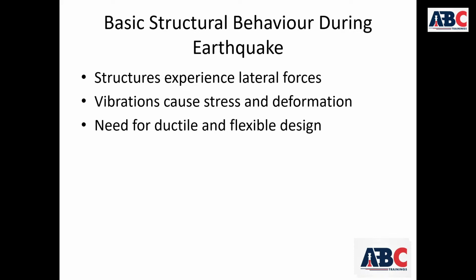The magnitude of the force depends on building mass, ground acceleration, and height of the structure. Heavier buildings experience heavier earthquake forces. That's why light structures perform better during earthquakes.